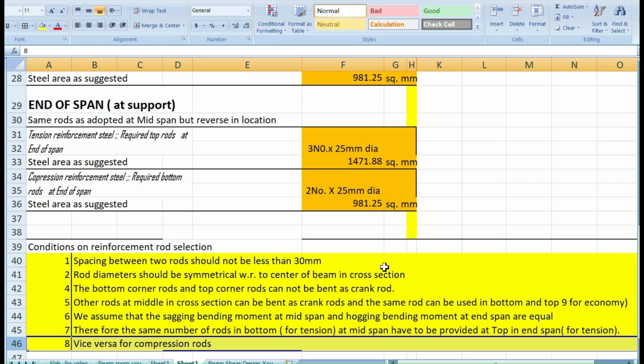Here we are required to note that T beams are not adaptable in any continuous beams, because in the T section the flange should be available only in the compression area. This can be applicable only in the midspan. If it comes to end span, the flange is in the tension area. So we need not worry about the flange availability. We can design as rectangular beam only for any continuous beams.